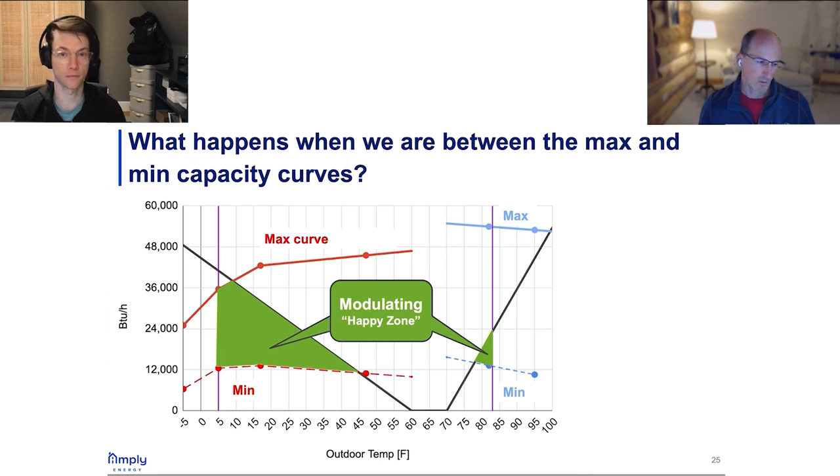Totally. That's where you get great energy efficiency. More importantly, that's where you get maximum comfort. You've got the equipment continuously running, so you've got great air filtration, which is really important for indoor air quality. You also ensure that you're really bathing all of your surfaces in the home with heating or cooling, which results in your mean radiant temperatures being where they should be to maximize comfort for the occupants.